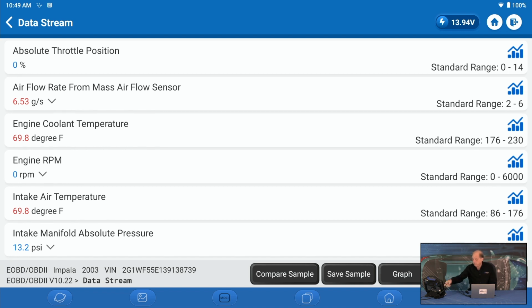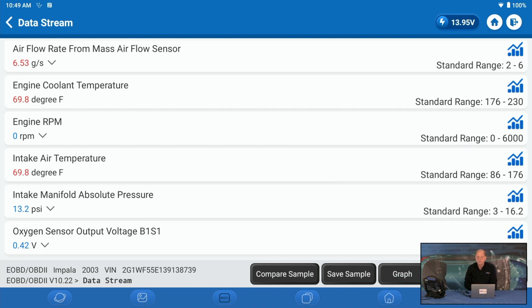So if we look at a process, now that's just to get me started. Then to get some more fine tune on it, I might want to use my O2 sensor. These are the 6 main inputs you're going to be looking at for a vehicle. So it's a really good idea to set your scan tool up on a car that's got some problems, or if you're a student and you're starting to learn this stuff, you want to be able to look at the main inputs and see how they interrelate to each other to get a good idea what's going on with the vehicle.